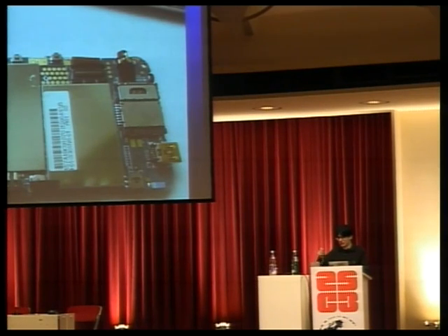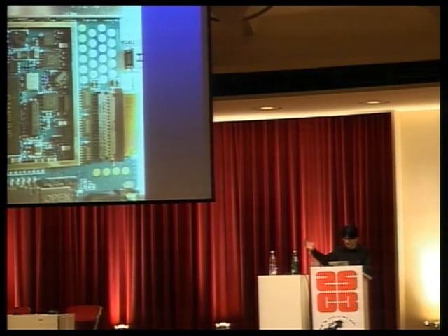So you actually, with a small screwdriver, maybe a scalpel, you can try to lift them. If they're soldered on, then you actually have to unsolder them or cut them open with the scalpel, which is what I did on one of my Motorola phones. So this is the uncovered application processor section. So we can again see the Samsung system on a chip in the center. This one is the CPLD, which they use for various peripherals like keyboard scanning and so on.